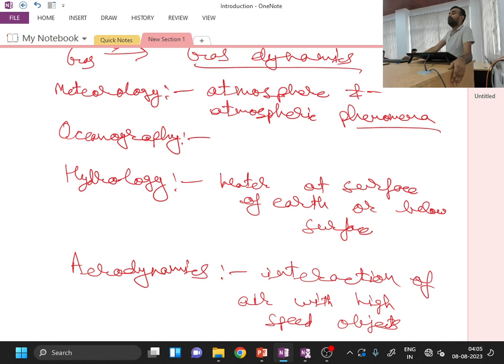So nowadays people are trying to fabricate very small channels passing through these electronic components, and the size of these channels can be of the order of say 5 micrometer or so. They pass high energy density carrying fluids or high conductivity fluids through these channels, so that these fluids can effectively extract the heat from these devices, so that the devices can be effectively cooled and work properly.